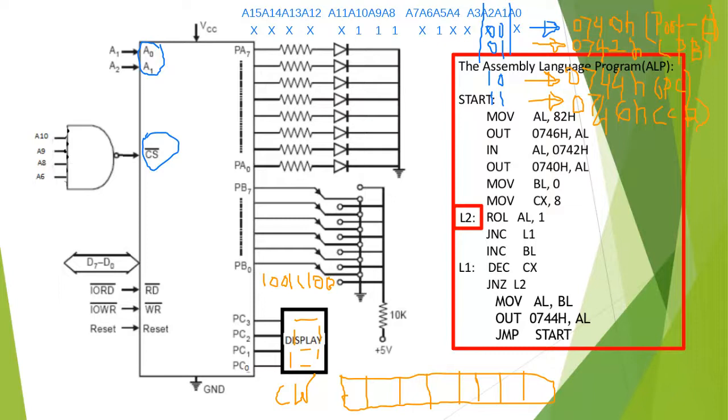So in our program we have to find the number of 1s. We did this kind of problem previously, like how many ones in a 16-bit number. The same way, it's very simple. You make the rotation, either left or right, and we check the carry flag.